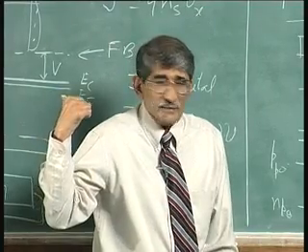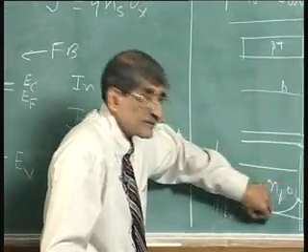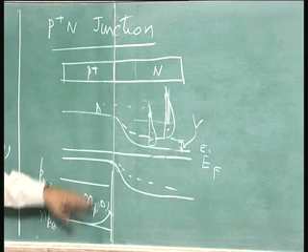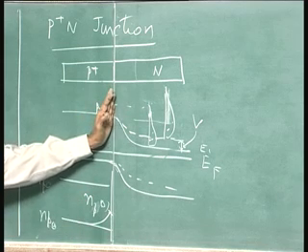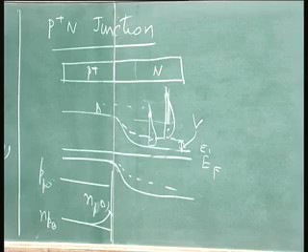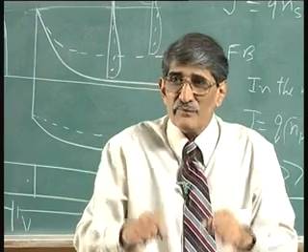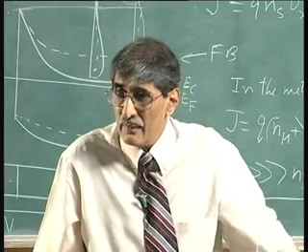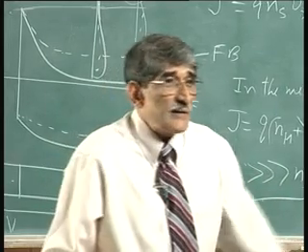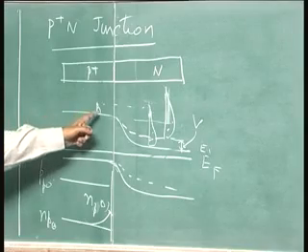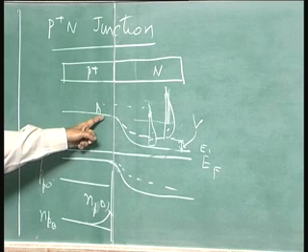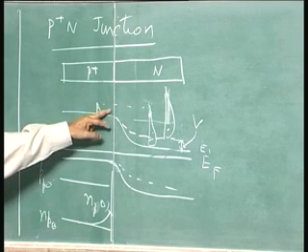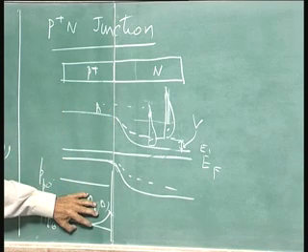In the p-n junction, this process is slow: diffusion, where the driving force is the concentration gradient. This process is faster. So, these are two processes in series. The slower one controls the current flow, the slower one is the diffusion, and that magnitude is much smaller than what is crossing there. So, this is smaller compared to what is crossing there, and this is the total current, which is actually given